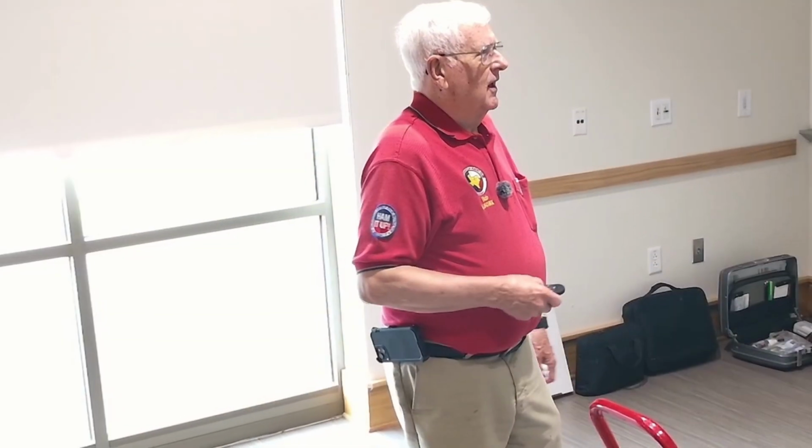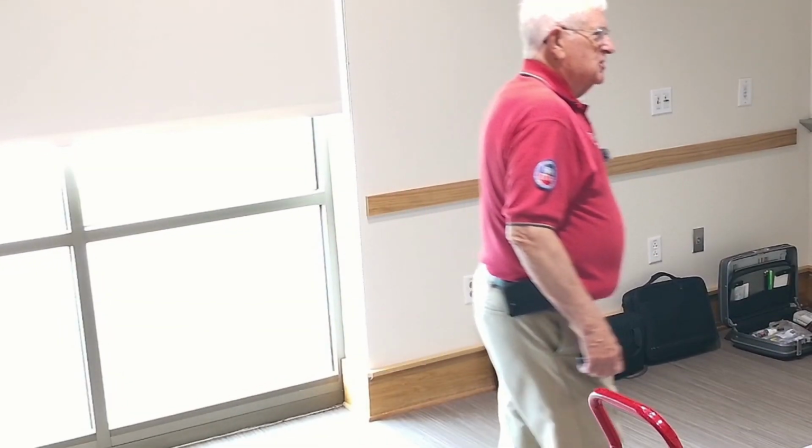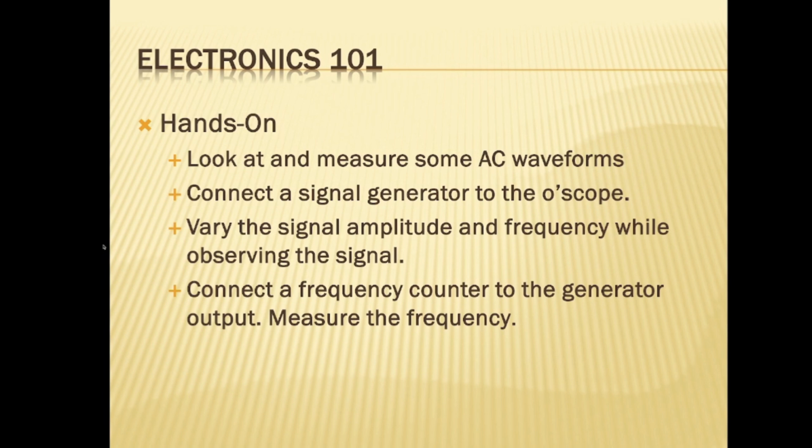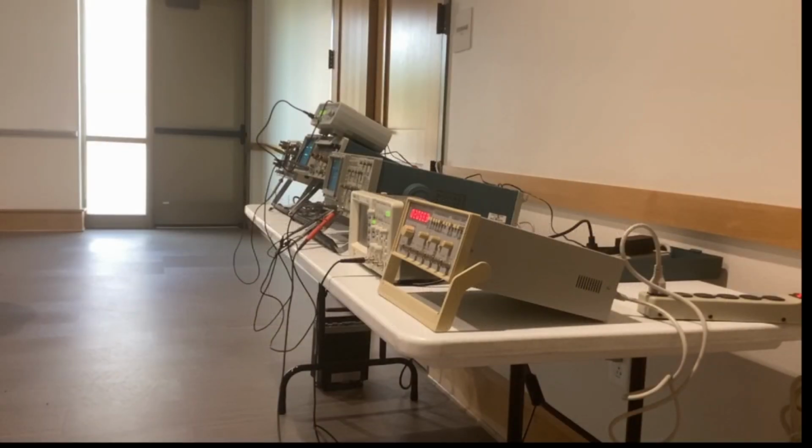All right. With that, let's do some of that stuff. At this point, we're going to have to share a little bit, so kind of go around and do these things. There are 2 signal generators over there, and then 4 oscopes. Just hook up there. You can vary the signal generator to give you different frequencies if you want to. And then you have to sync the scope to make sure it'll see the signal and be stable for you.